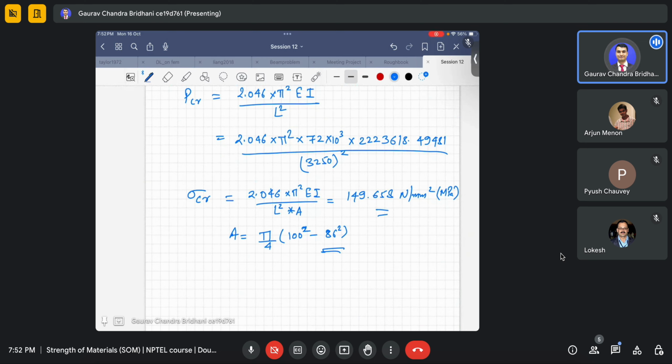So that's how we find the value in the design problem, because it's basically a design problem. You have been given a load, and then you have been asked how much the value of the diameter will be. You need to find it, and then you have to again check for the diameter whether your proportional limit is exceeded, which should not happen at any cost.